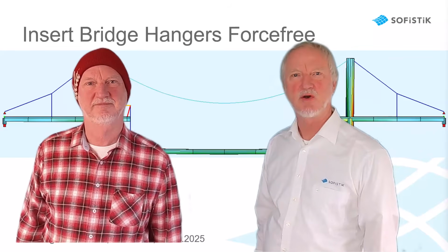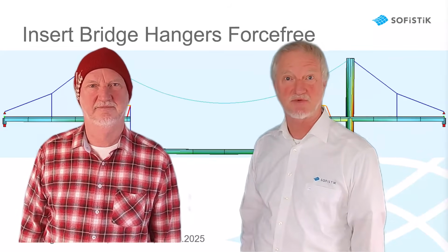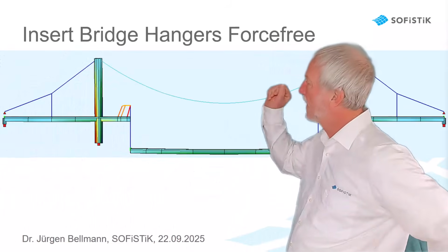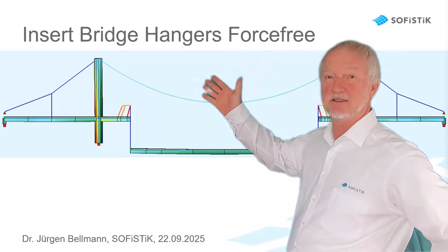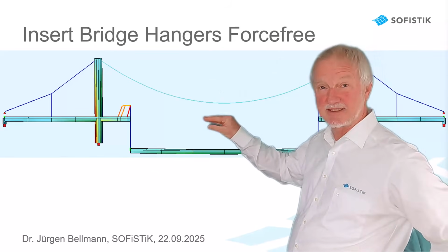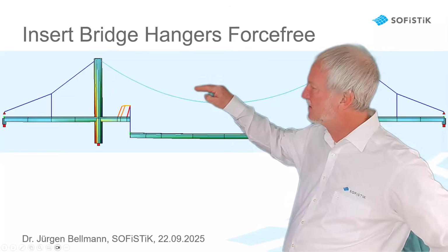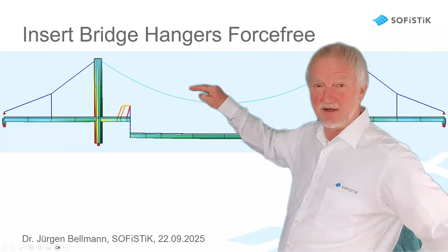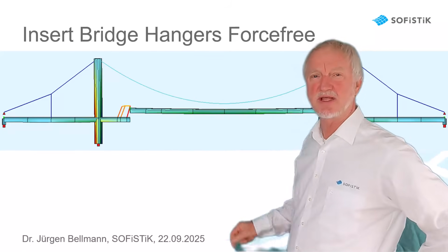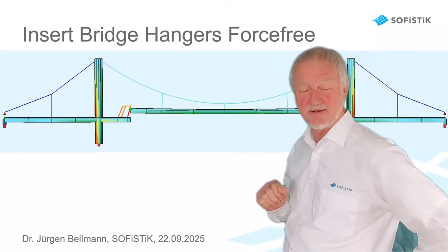In this video we would like to show you how to insert hangers force-free. Now, what do we mean with this? When we have a little suspension bridge, we ship our last segment to site and then lift it to the final level, but then lift it a little bit higher so that we can then insert the hangers force-free.